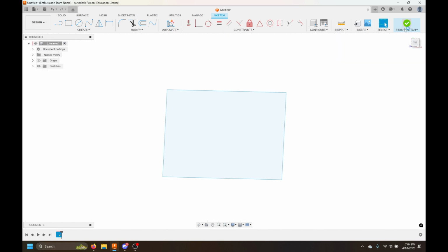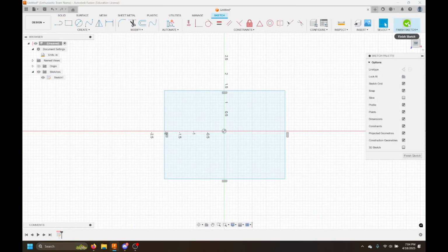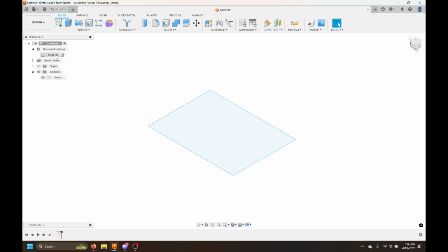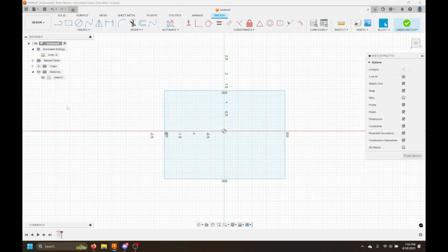Okay. That's changing. It's an easy fix right here in document settings. You got units, and then you do change active, and then it's over here. Oh, I have to finish my sketch first. Oh yeah. Alright, document settings, finish sketch button, Units is in the top right. And inch. Okay, sweet, and then I can go back into sketch and edit. Yep. You can right click and then edit sketch is one of the options, or you can double click on it in the menu.